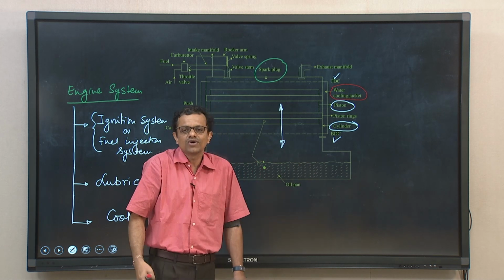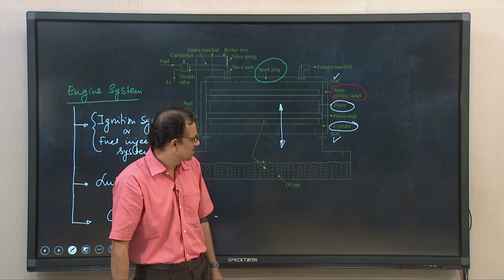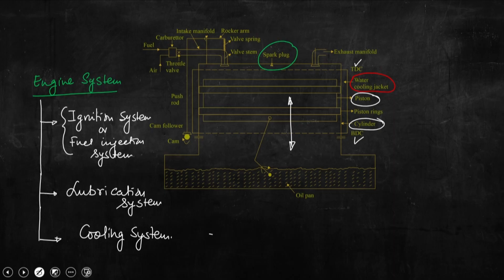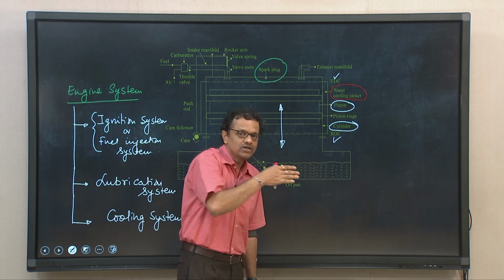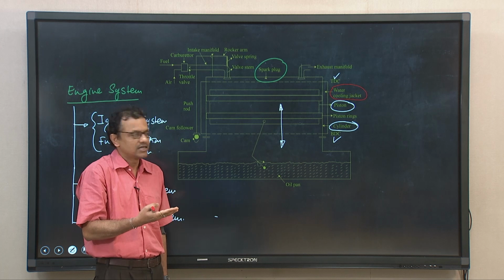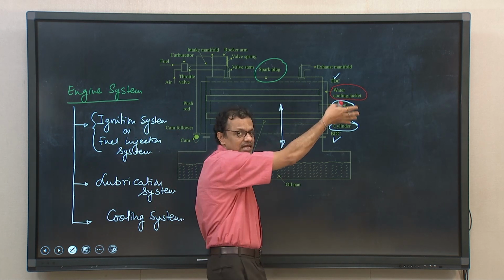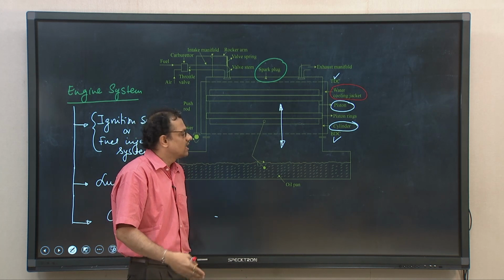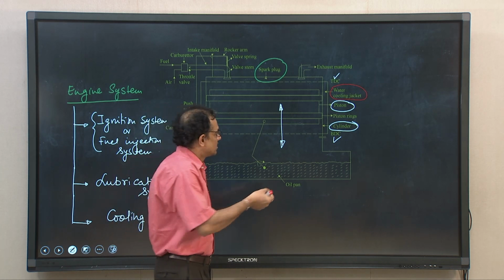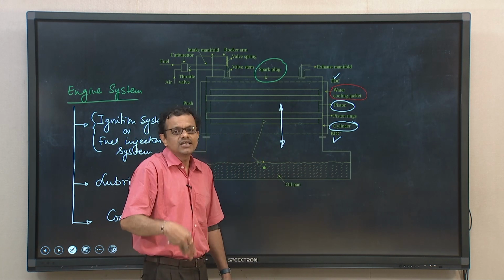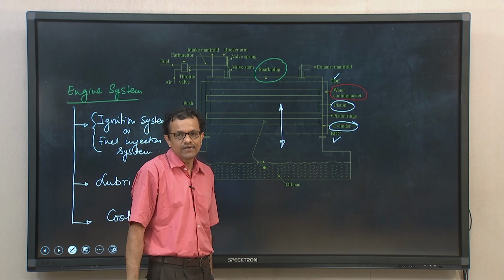No, because that is what we have learned from basic thermodynamics. So, certainly a certain amount of heat needs to be transferred from the combustion chamber into the ambience through the cylinder wall. If we do not have enough provision for the transport of heat generated inside the combustion chamber into the ambience, that heat will lead to several other mechanical issues like development of a crack, or the engine cylinder might break. All these detrimental effects will be there.